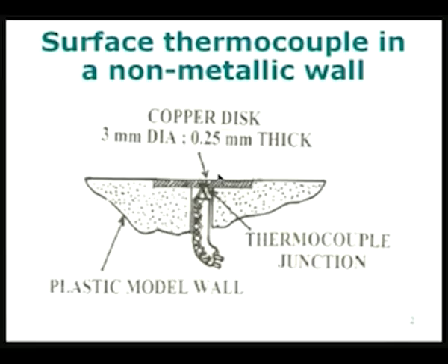So we expect that if the velocity is big enough, the difference in temperature of the fluid and the surface will be very small. So, the temperature which we measure can be used as a measure of the effectiveness of the heat transfer which is taking place from the medium to the surface.